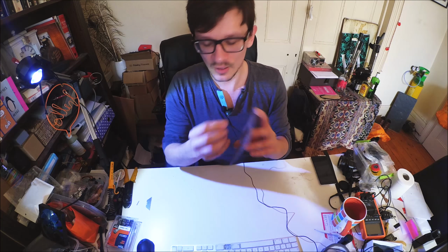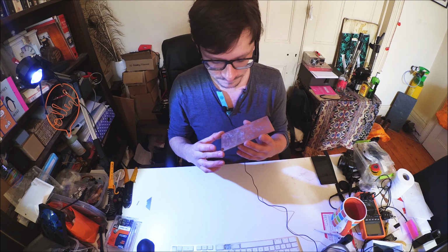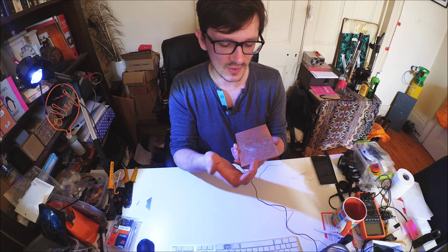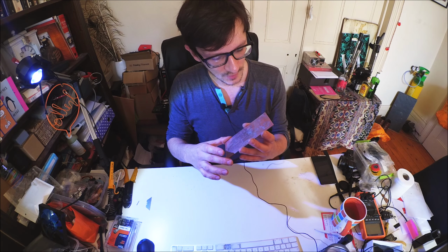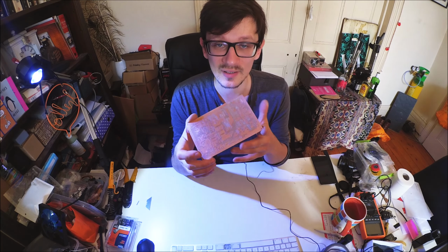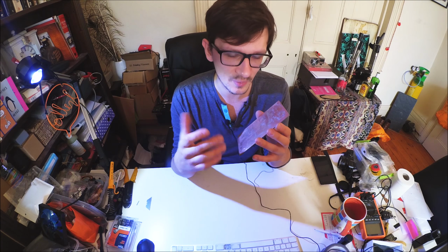Now if you can't access the top, like for example if you're soldering a serial header, where it's blocked from one side and you can't access these pins, I'm going to basically try using solder paste, putting solder paste on the pins and then pushing the component through, and hopefully the solder paste kind of creates a little ball of solder on the top layer, and then when you solder it from the bottom, the heat will hopefully fuse it to the top as well. I haven't tried this yet, but it seems a hell of a lot easier than going through the plating process.